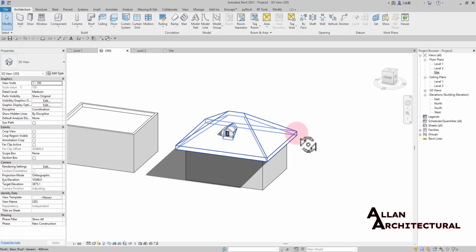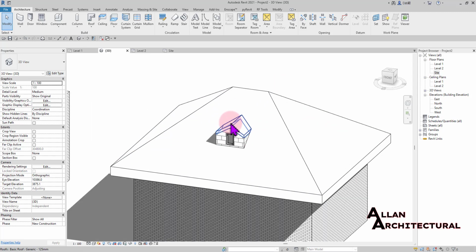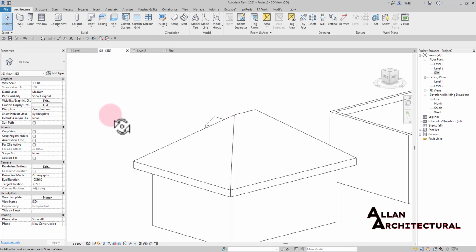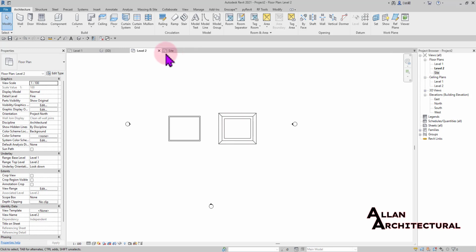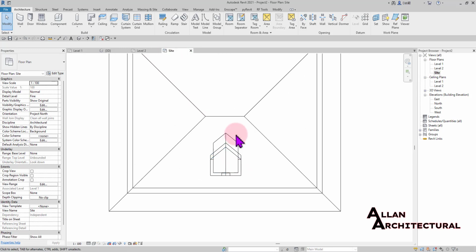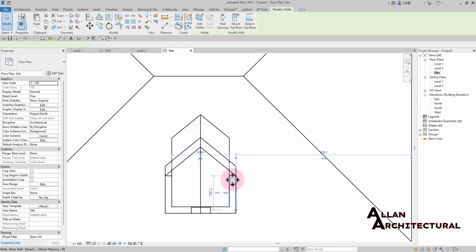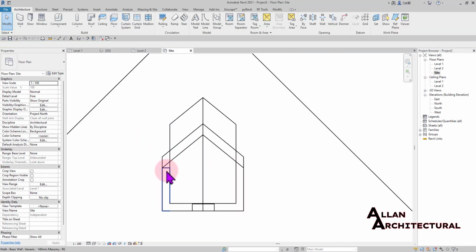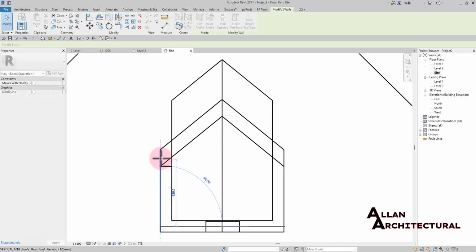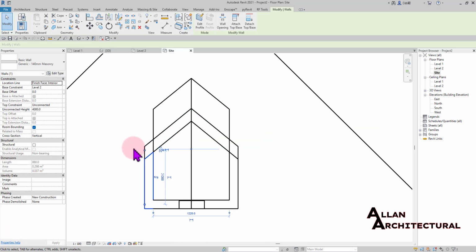So we can use our extrusion tool to create a unique dome roof in there. So we can head back in here. Let me just create one roof by extrusion in there. So we can select this wall and then we extend it a little bit so it covers that. Select this and then we push this to enter in there, and this is perfect.